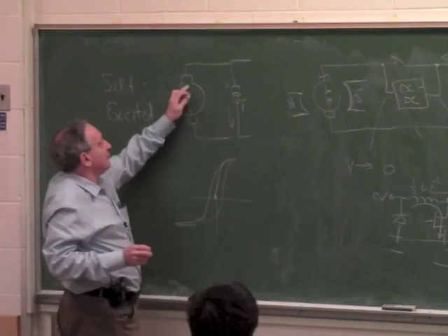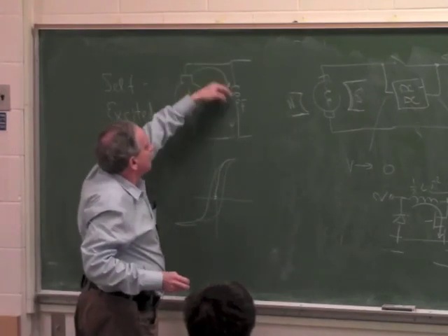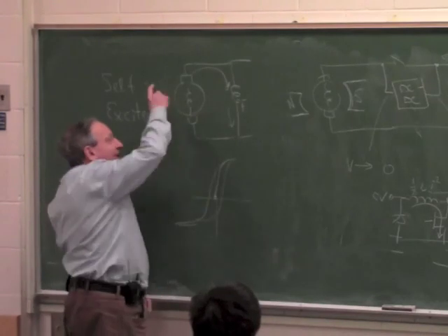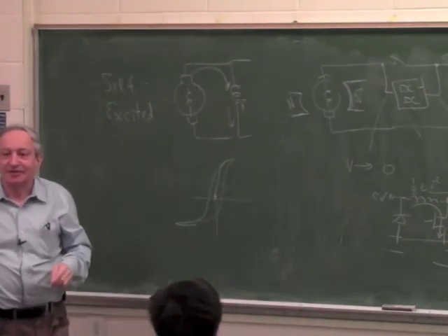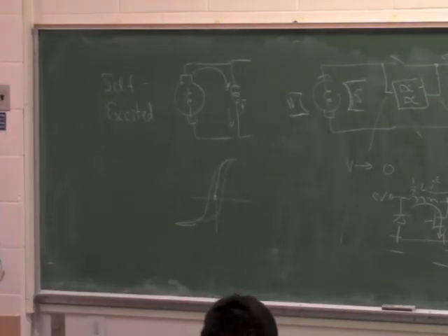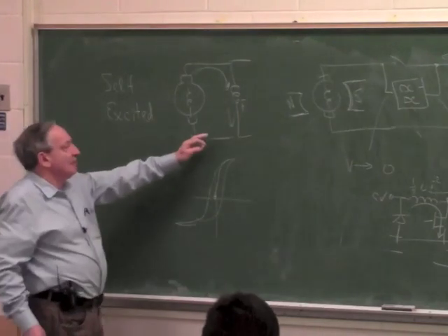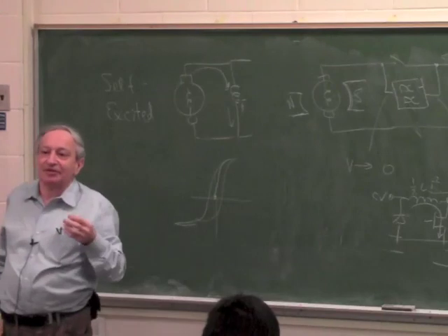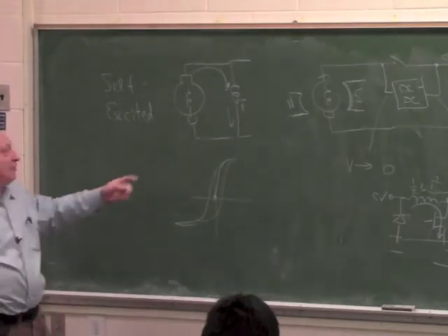Now this little bit of voltage creates more current and creates more magnetism, which creates more current, so it's positive feedback. That's why even if a motor doesn't have a permanent magnet, it will still become a generator. Especially for parallel wound.